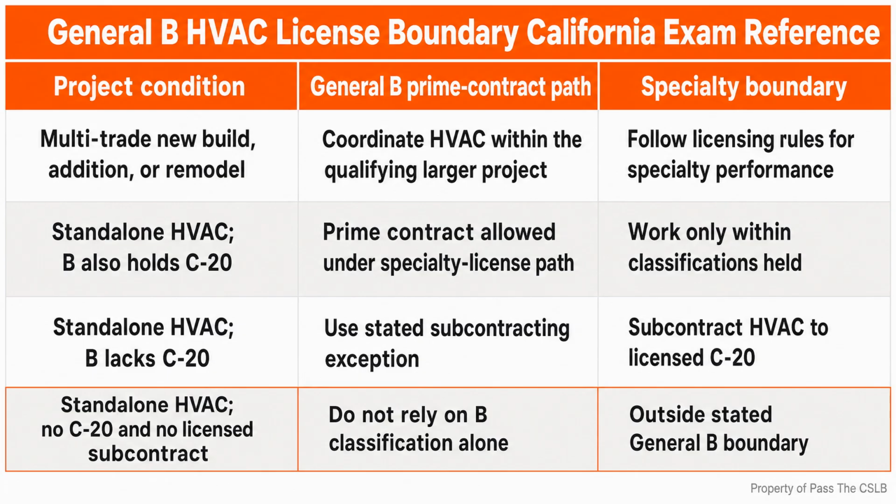A bigger unit is not automatically a safer choice. A bigger unit can cool the air so quickly that the thermostat shuts it off before the system has operated long enough to manage moisture well. The result can be a house that reaches the temperature setting but still feels damp and clammy. That is the central connection I want you to remember. Load calculation is not paperwork for paperwork's sake. It is the bridge between the building that was actually designed and the equipment that is actually installed.